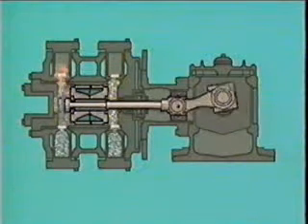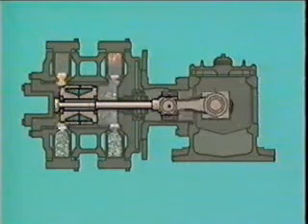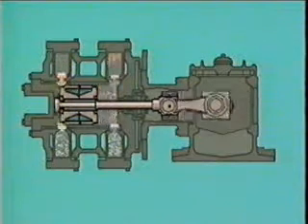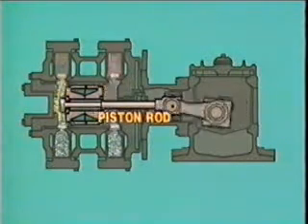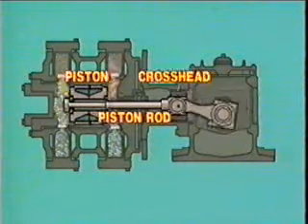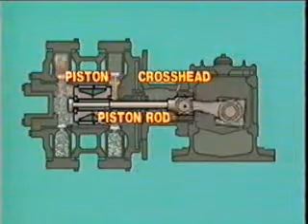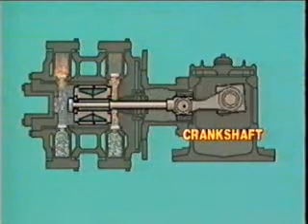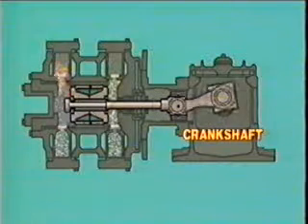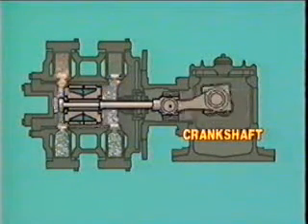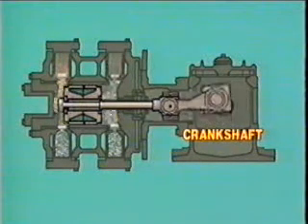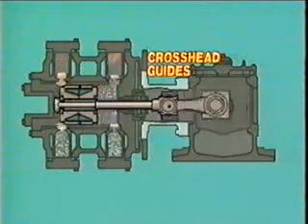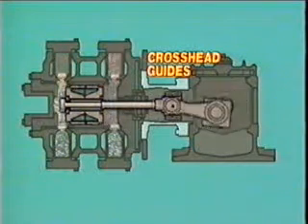Within the compressor, there are two types of rods: piston and connecting. A piston rod joins the piston to the crosshead. The crosshead converts the rotary motion of the crankshaft into the back and forth motion of the piston. The crosshead must be held in very close tolerance to the crosshead guides to ensure horizontal, level motion of the piston.